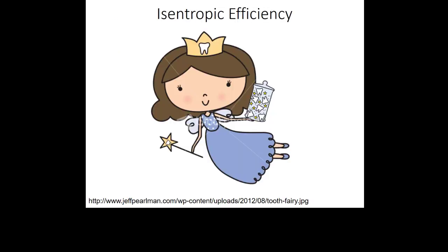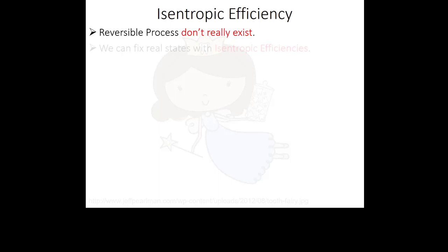Okay? Now, I've said a couple of times that when you're thinking about these cycles that have air as the working fluid, it's really important to know where the isentropic processes are. Of course, the real answer to that is that there are no isentropic processes. So really, it's where could the isentropic processes be, right? They don't really exist, but anytime I'm talking about a component that doesn't have heat transfer related to it, right, then I could have an isentropic efficiency.